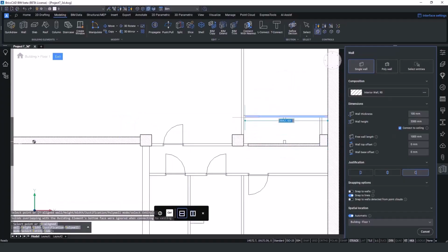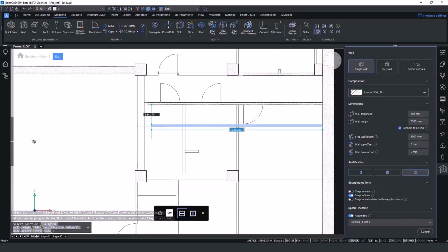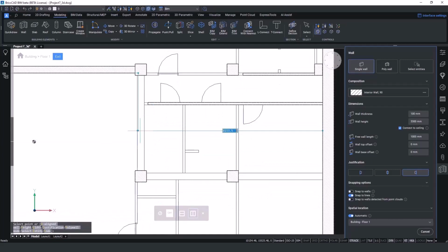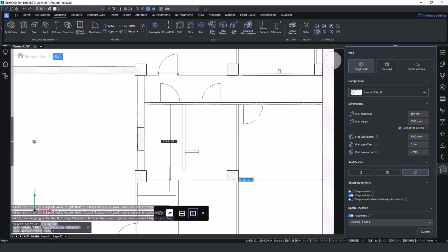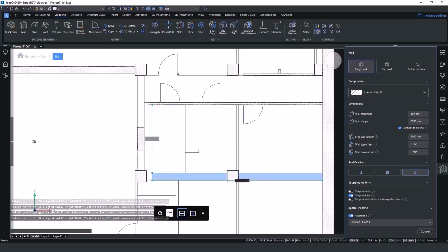This smart behavior can also be used with point cloud data. By pressing the Control button, you will be able to swap direction for a better interpretation, and then finish up with the Beam Extend tool.